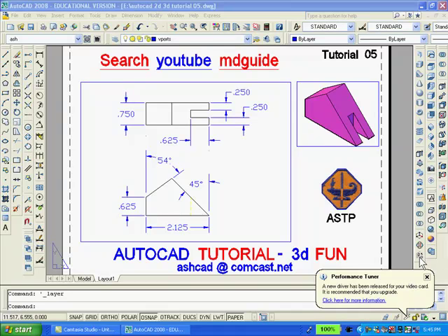What you are looking at now is my 2D drawing and solid model of the object. If you look at the icon in the lower left corner of the screen, you can tell that the drawings being displayed are in Paperspace because a small right triangle is shown. The first thing to do is to erase both the large and small viewports.